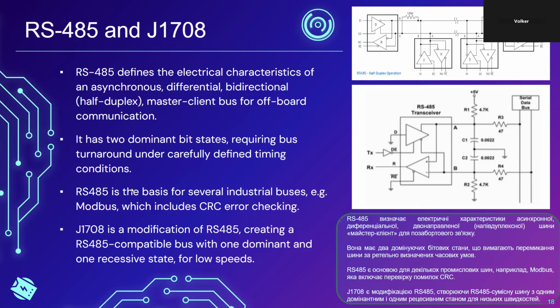So if, for example, you are in an old factory and there is old telephone cabling between buildings, and you just need a sensor temperature result, or some kind of sensor signal that you need to transfer from one building to the other building, and there are unused telephone wire pairs in cable ducts somewhere, RS-485 can do that.